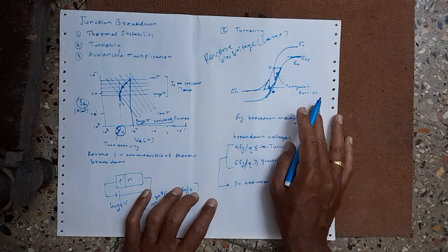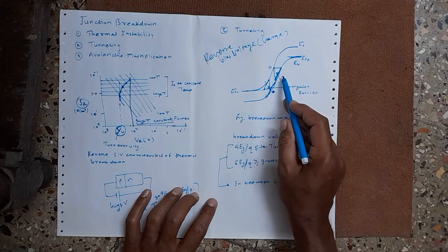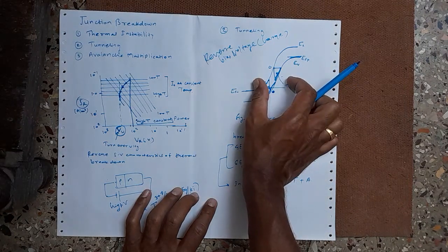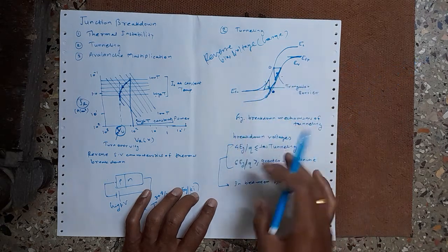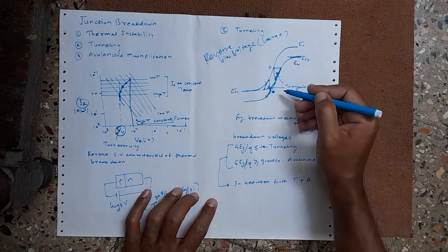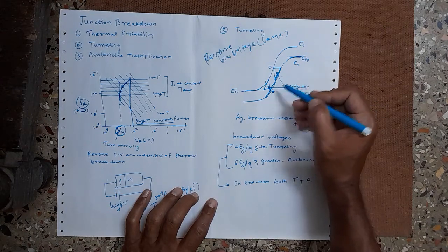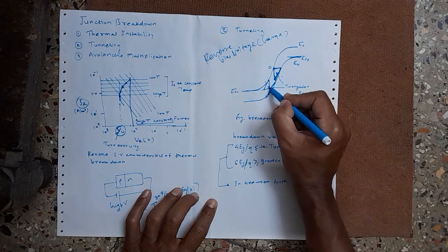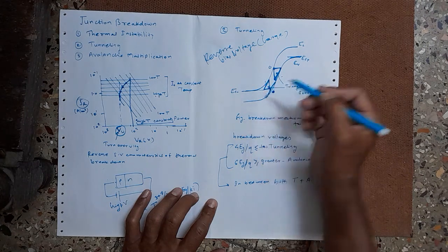The tunneling phenomenon is most of the time related to the field effect, because the potential is applied across some distance, and the potential over distance gives us the electric field. So in this particular case, the barrier has a triangular shape. It is a triangular section over here, and here also it is a triangular one.